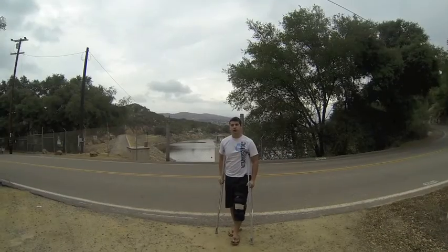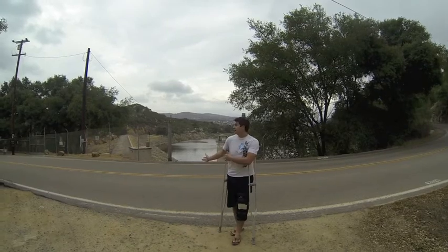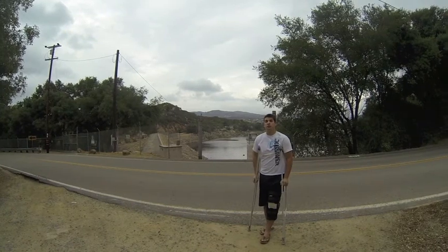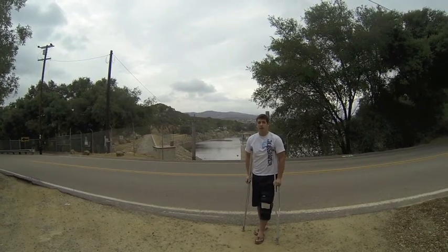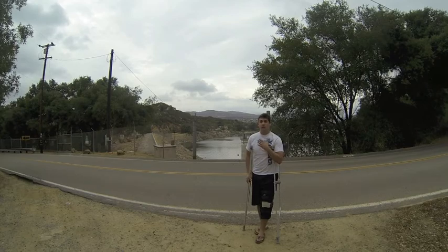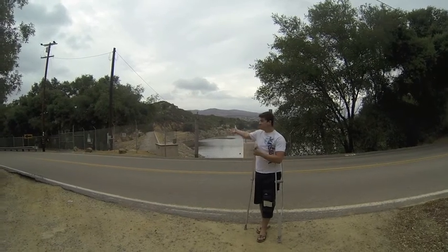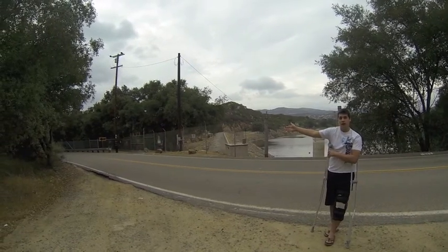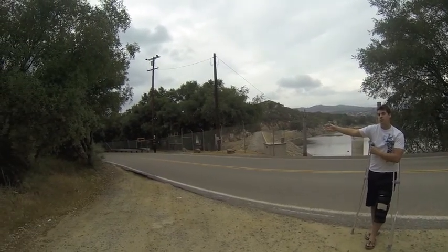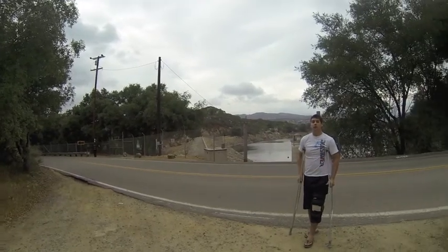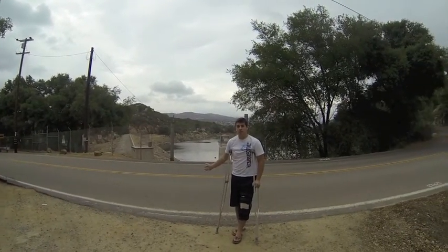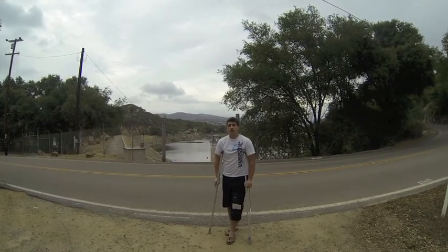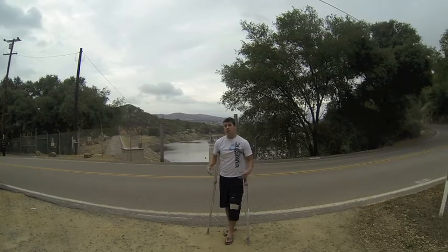Hello, we are at the current Lake Wohlford Dam. As you can see, the hydraulic fill layer is on top of the dam. We are planning on replacing it to be about 50 feet from the toe of the dam, and it would actually envelop the bend in this road, so this road would have to be moved. We are also planning on notching the current dam so that the replacement RCC dam would feel the full effect of the water being held against it, so that it would be a complete system.